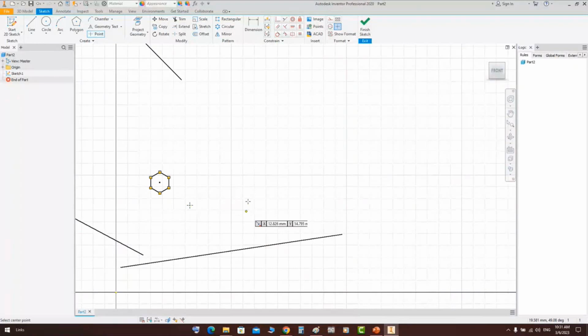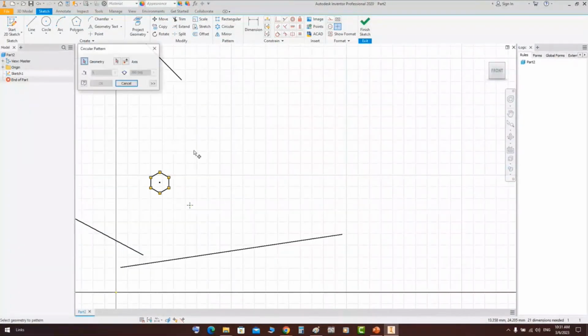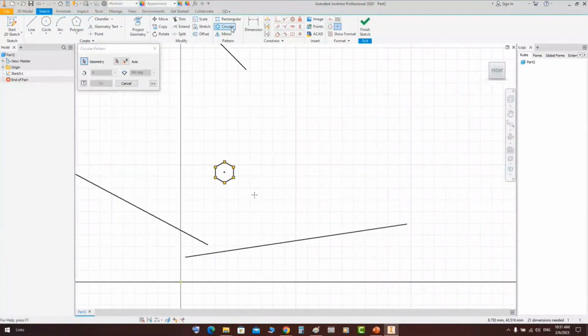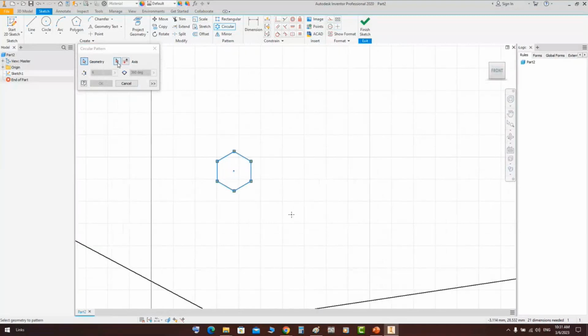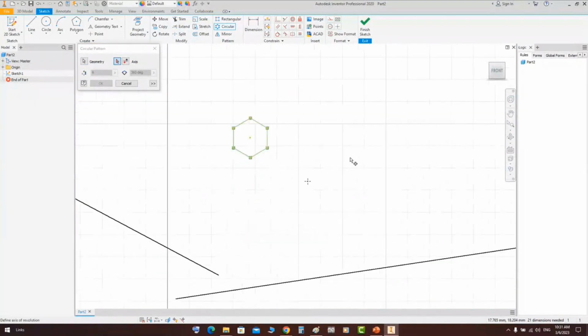Now let's make a circular pattern. If we have a point here, by the circular pattern, when you open this form, you will be able to select the geometry of the feature. After that, you will be able to select the center point of the rotation. For example, if you would like to select this point, or that point, in our case, let's select this point. Now you will get this pattern like that. And you can figure that the orientation direction will be counterclockwise. If you would like to flip it, you can flip it from this axis.